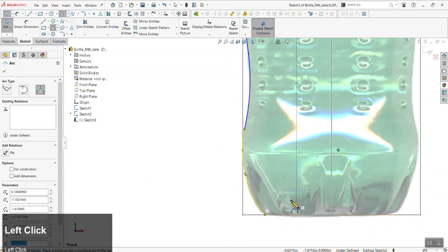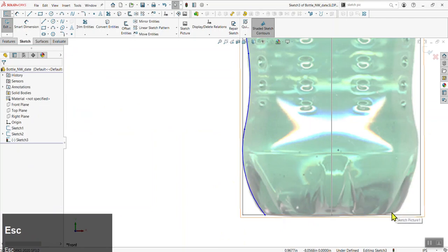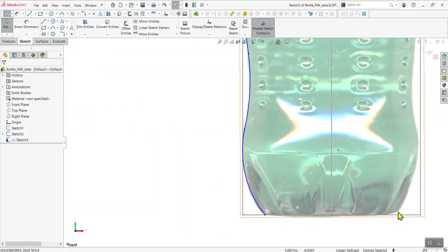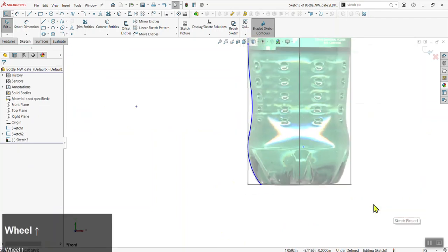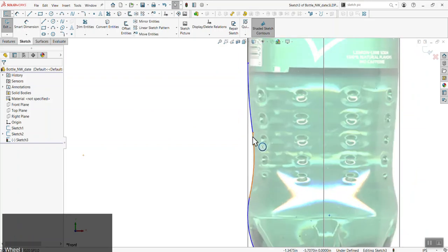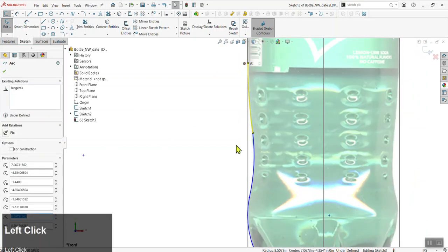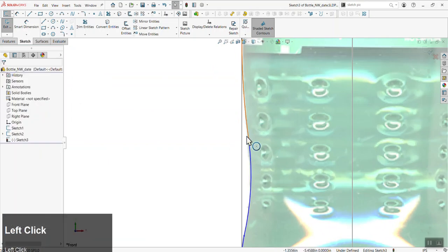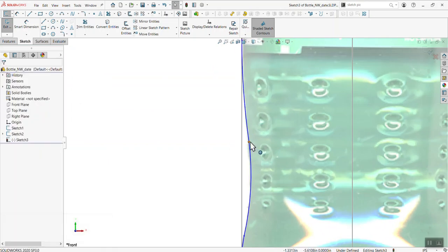And again, there is a curve on the bottom of the bottle here, but to me this is a detail curve, not a design curve. So that's going to be a fillet. Now the one thing to be aware of as you sketch these arcs is they really should all be tangent. If you don't set the tangent relationship, you'll get a seam across here. We're not going to render this bottle, but if you did, that seam would show up. It would be kind of a harsh break.